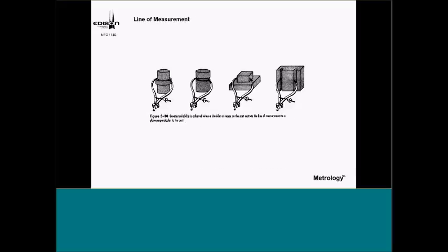And I talk about line of measurement quite a bit. We're going to start getting involved with this, especially when we use precision measuring instruments, but you might as well get used to it right now. I said if you can use a shoulder, it's really reliable to do that. Trying to get the correct line of measurement. It's basically perpendicular to the part.